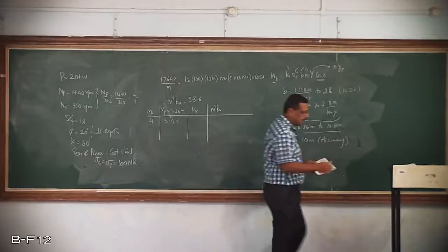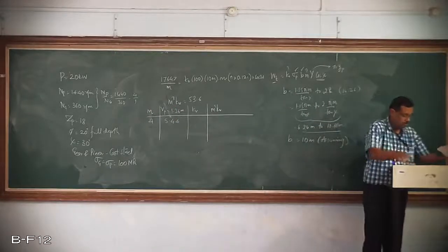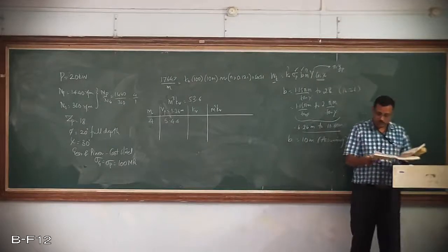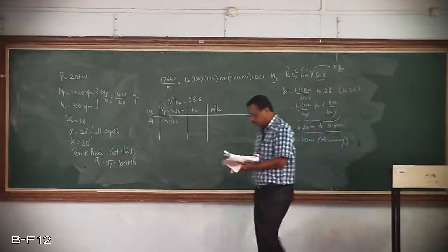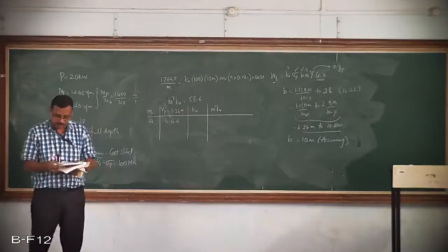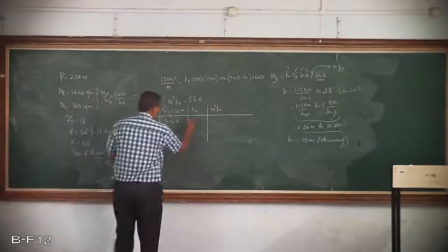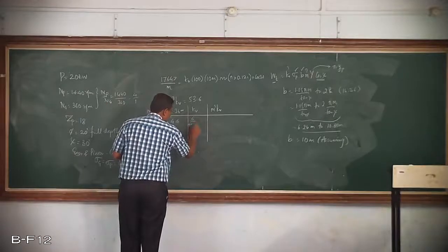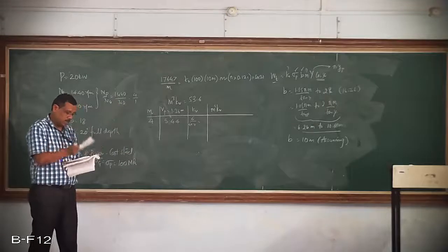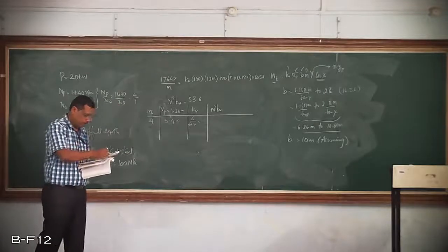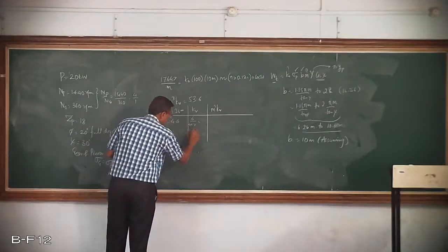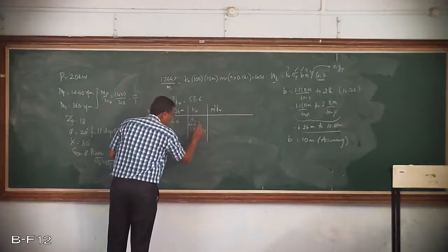Now I will refer to the data handbook for the velocity factor. For 5.44, the first one, 16.32, is less than 5. Therefore, between 5 to 10 meters per second, it is equation 16.33. Therefore, kV will be 6 divided by 6 plus V. The V I will be taking as 5.44, and that comes to about 0.524.